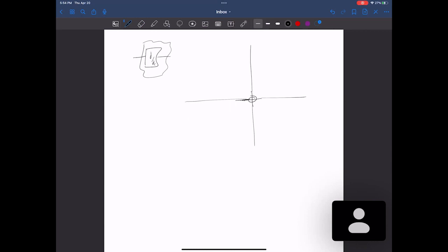So what people do is add a low pass filter. The best way to add the low pass filter is to represent it as a pole. We could add a pole somewhere on the real axis, and the further away it is from the origin, the less effect it will have over the whole system, so the less effect it will have over our dynamics. So let's say we add the pole at minus 100. This is the differentiator, and we wanted to add a pole at minus 100 to smoothen it out.